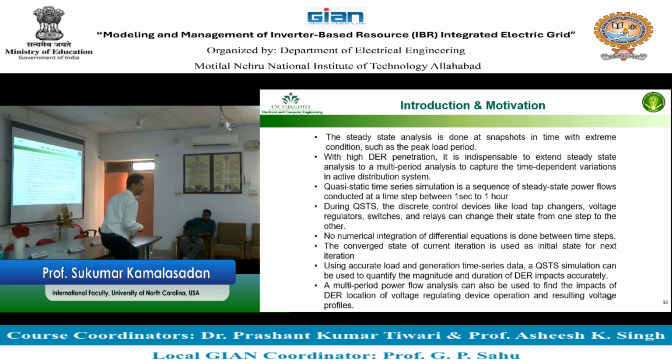What happens if you have a change in the load in an electric grid? How do you run a power flow? In a power flow, will you change the loads? When you run a power flow one time, the load is constant. Oh, is the load constant all the time? Load is changing. What happens if the load is changing? What do you do with the power flow? You run power flow multiple times.